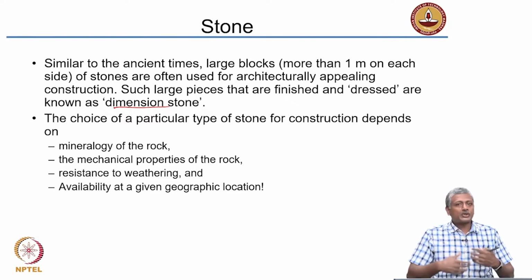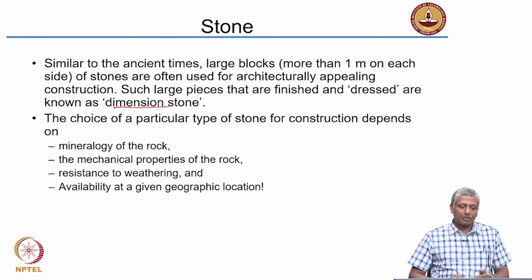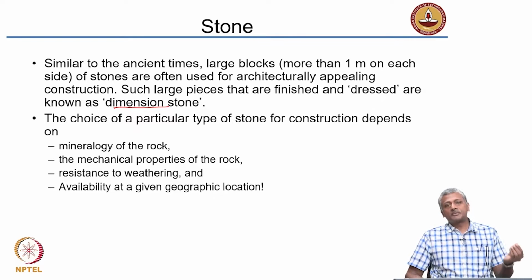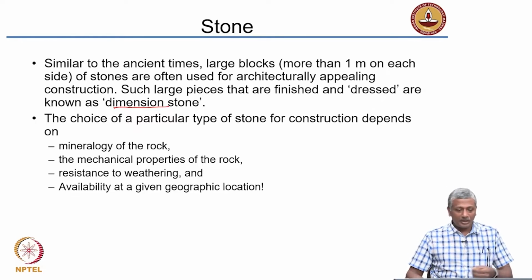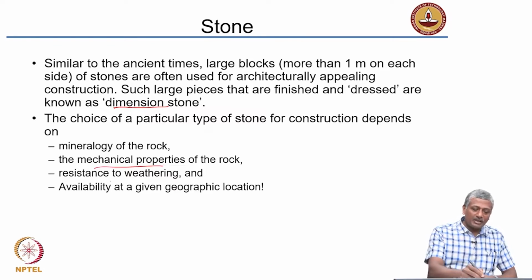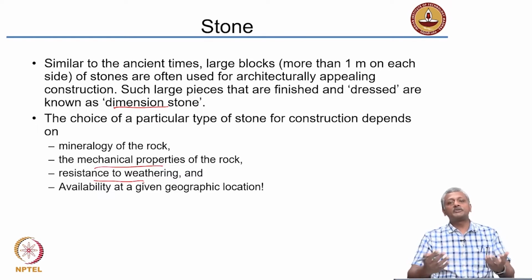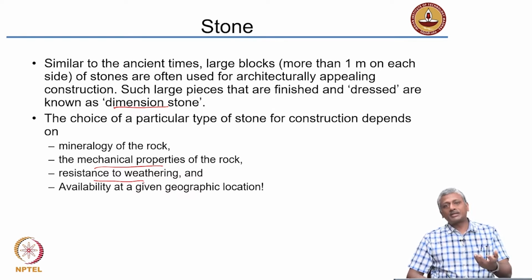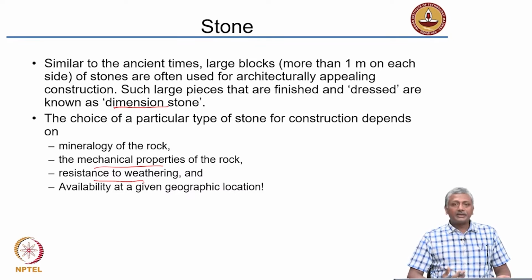But nevertheless, you also have to be worried about the engineering properties that are made possible by the specific mineralogy of the rock. Okay. The other mechanical properties and resistance to weathering obviously are performance related aspects, and those are absolutely important to ensure that you are able to build a structure that is going to last for a long time. Okay. So, we call that durability, strength and durability, or in the case of rocks and stones, we call it mechanical properties and resistance to weathering.